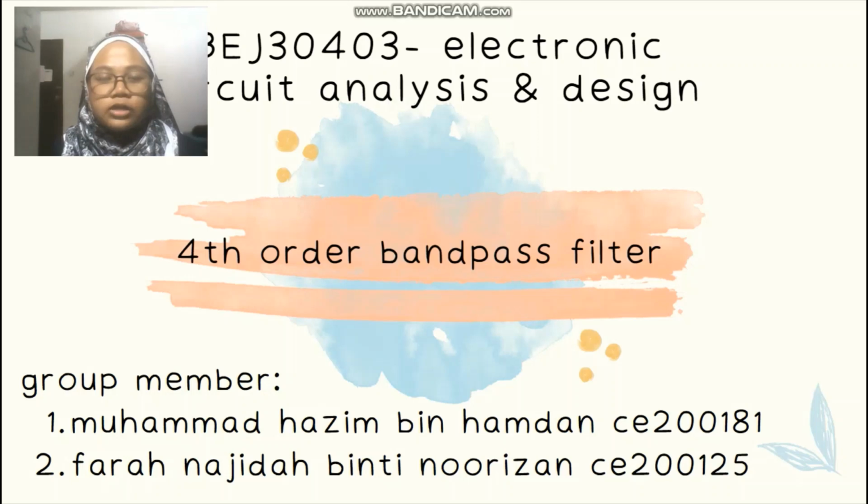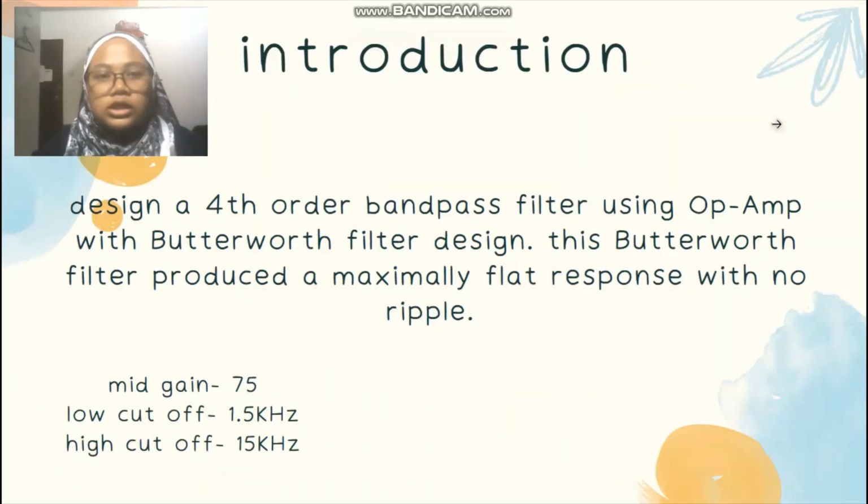Me and my group member, Muhammad Hamzi bin Hamdan, are going to present our project on the bandpass filter. A little introduction: we are required to design a fourth order bandpass filter using op-amp with a Butterworth filter design, which will produce a maximally flat response with no ripple.